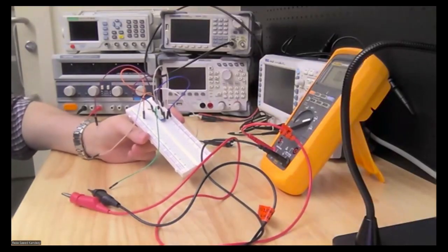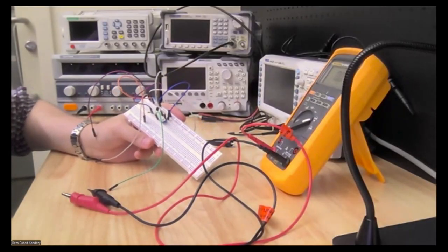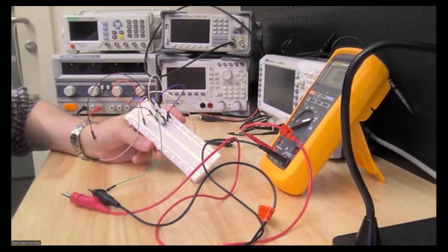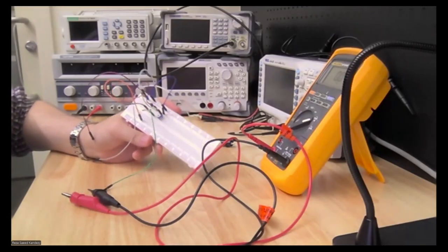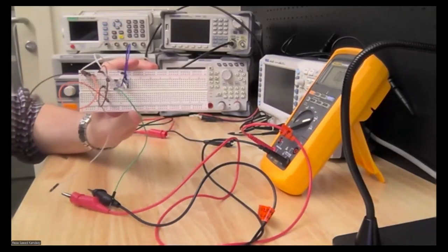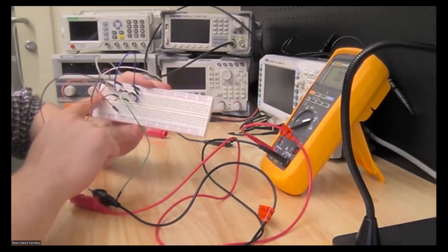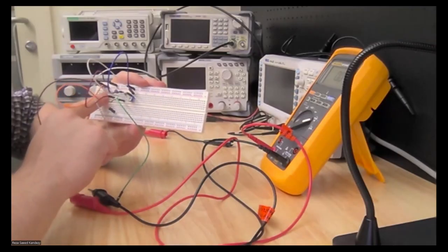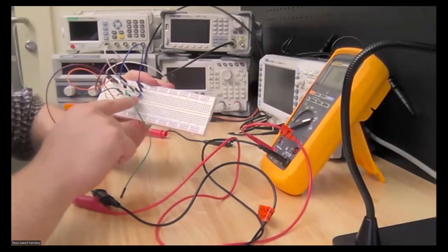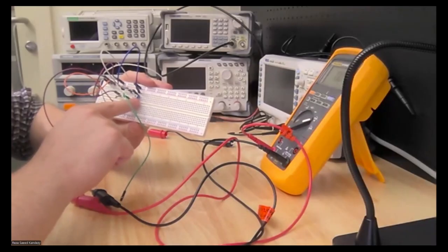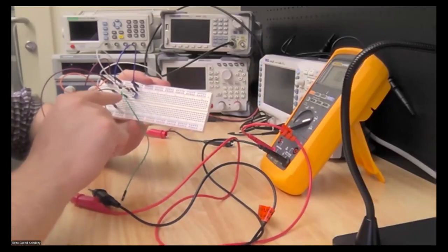Okay, now let's move on to the actual experiment to see what the IV curve and the beta measurement are going to be for our BJT. Now, as you can see, I already created the circuit. So I have a voltage source which is connected in series to the transistor, to the BJT, using a resistor. And I also connected the same voltage source through another resistor to the base